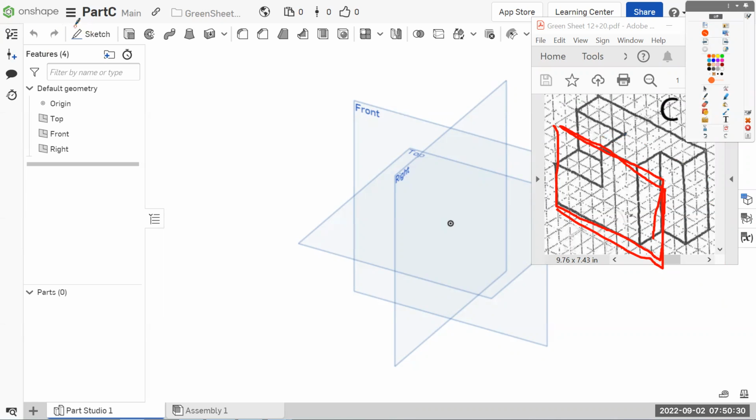Okay, so sketch is 2-dimensional drawings. When you're done with the sketch, you then do our part tools, which are 3-dimensional tools. We're going to take that rectangle and extrude it a depth of 4, and that will give us our block. That's the maximum size in all 3 dimensions, height, width, and depth, and cut away what we don't want.